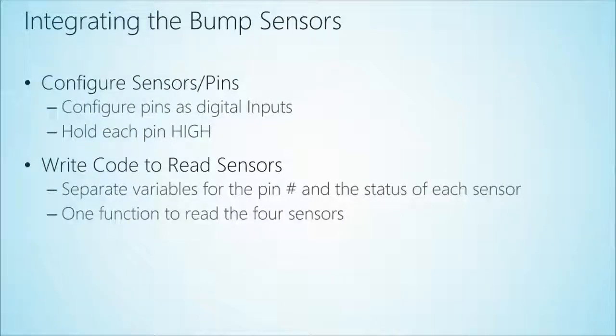All right. So we have a slide we're going to talk to here. Right there. All right, here we go. Sensors and pins, configure them. We've done a lot of that, Paul. Sure, we have. But basically, you just tell it what pin you're using. It's a digital pin because we're going to read it. We hold it high. Remember how we did that? We did the digital write to hold it high. That uses the internal resistor on the Arduino board to hold it up high until it gets pulled to low, pulled to ground, which the switch does. And again, if you missed that or you're just joining us, check Module 2 out. We talk about all those things in Module 2 when we show you how to program that.